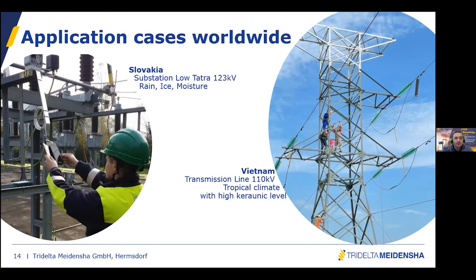So last question, I want to go a little bit deeper: can we install smartCOUNT on distribution class arresters and on medium voltage? Yes, that's possible. We have this limitation that we need the leakage current to charge up the device. This is typically around 200 microamps that is necessary to charge it. And normally this covers all applications from DH up to station high.